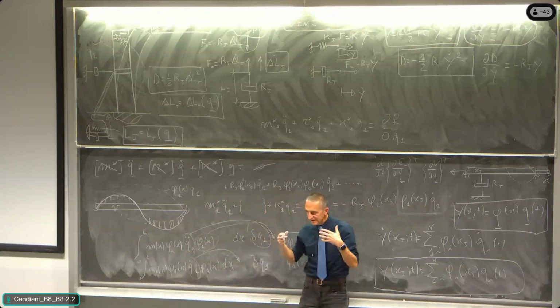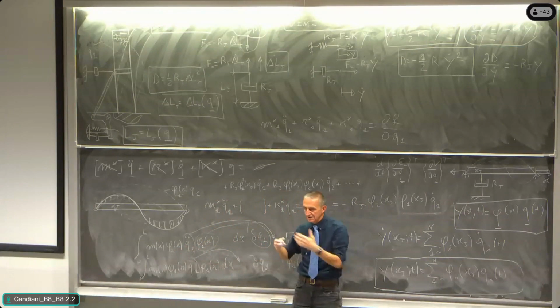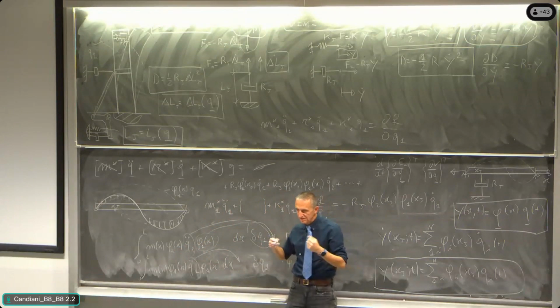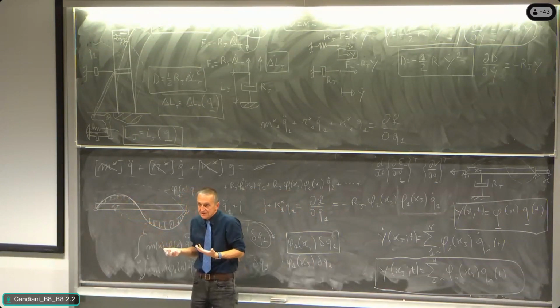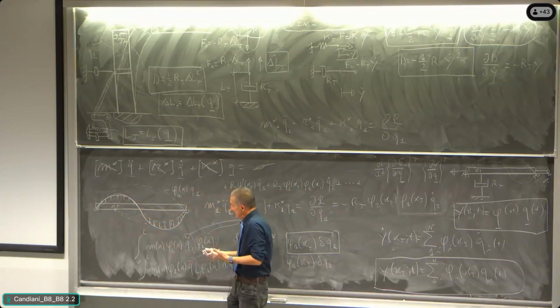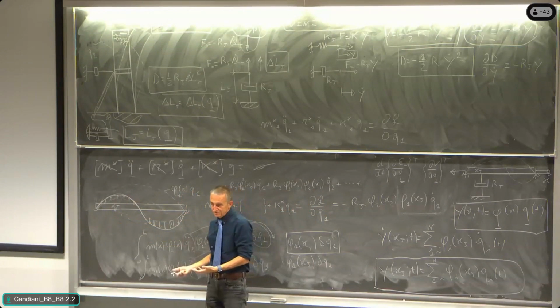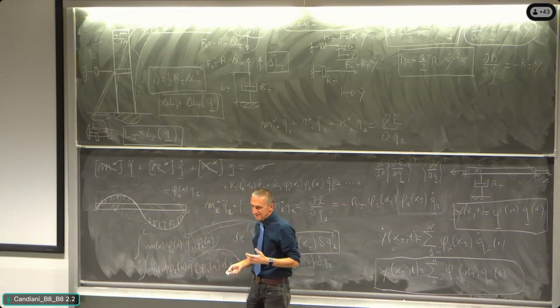And so the reason why I get the diagonal matrix in the effect of the inertial forces is because the inertial force is equal to the displacement, just scaled by omega squared. The shape is not changing. All right?